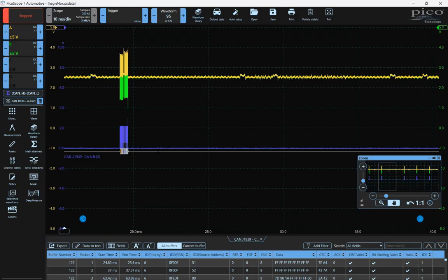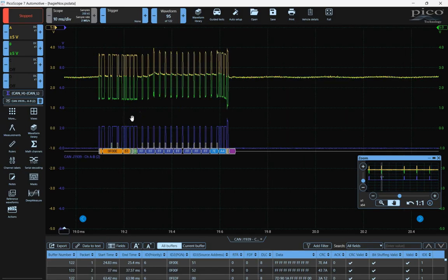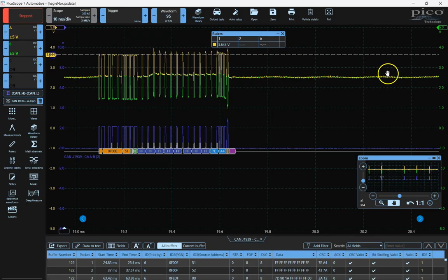Because it's the same voltage on CAN high and CAN low, it looks at the difference and we see it as 0. That's why we can look at this message, and even though you may be surprised to think, oh, look at this message, it's got a lot of problems with it. Look at this, it goes up and down, it's got these peaks. This is real data. This is what it looks like at times. There's nothing wrong with this data.